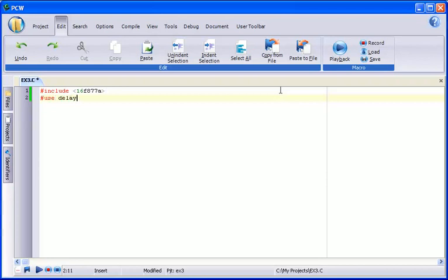The use statement specifies the oscillator clock frequency. The value specified for the clock frequency will be used by the compiler later when built-in delay functions are called. I have assigned a constant named green LED to MCU pin A5 with this define statement. This program causes an LED to blink continuously at 1 second intervals.